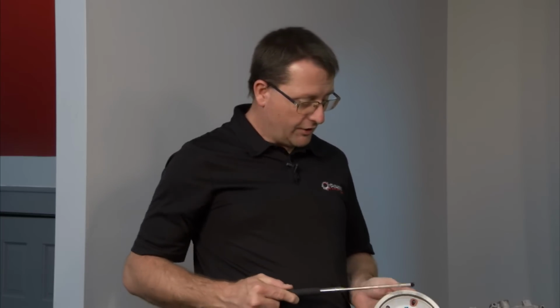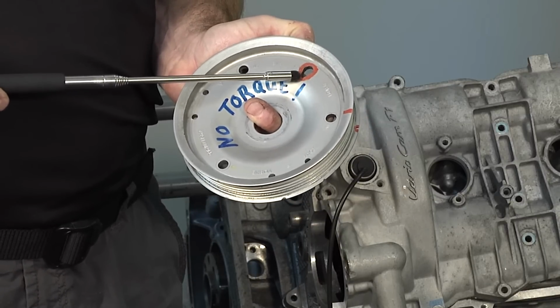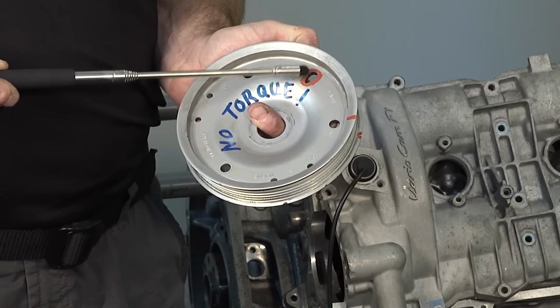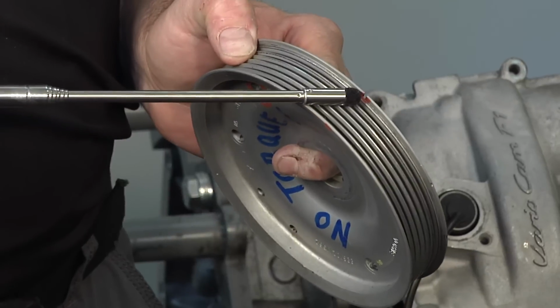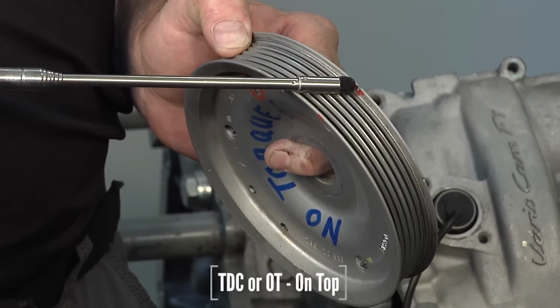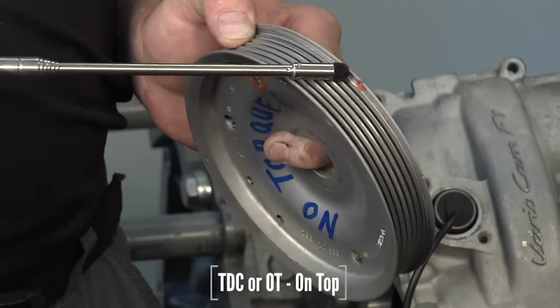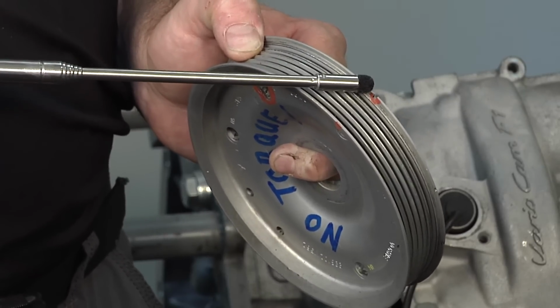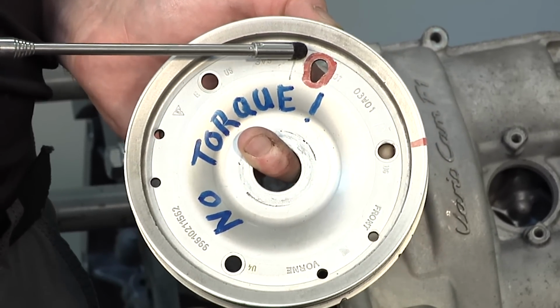So, first off, before you do anything mechanical with the internals of these engines from a repair perspective, you want to take your crankshaft position and lock it at TDC. Now, TDC is indicated as basically the teardrop here on the crankshaft pulley, and when the teardrop here aligns with the boss in the crankcase for the 8mm pin to go through and lock the crankshaft, you also have this notch align with the TDC mark, or OT, meaning on top, on the crankcase. So that will align over on the bank 2 side of the crankcase, while this aligns with the locking boss on the bank 2 side of the crankcase, okay?